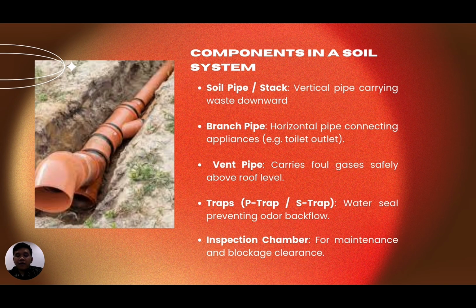Last but not least, we have the inspection chamber. This is essentially a dedicated access point, usually outside. It's crucial for maintenance and quick clearing of any blockages that might occur in the underground piping network.